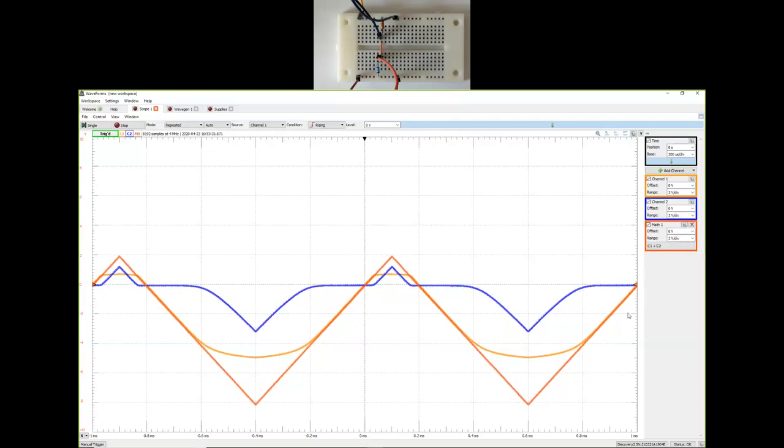If you take a look at the red triangle wave here, that was my wave gen. And if I take the diode voltage and add the resistor voltage, I get the source voltage here. So that's a quick check, that's how we are computing these values. We have a diode that gets limited to plus 0.7 and minus around 5. And whatever remains is going to the resistor. And that math channel was essentially used to check whether they add up or not. And it looks like they perfectly do.